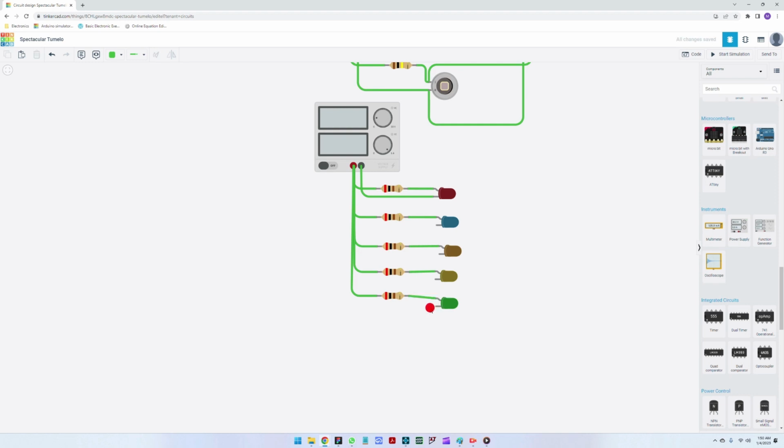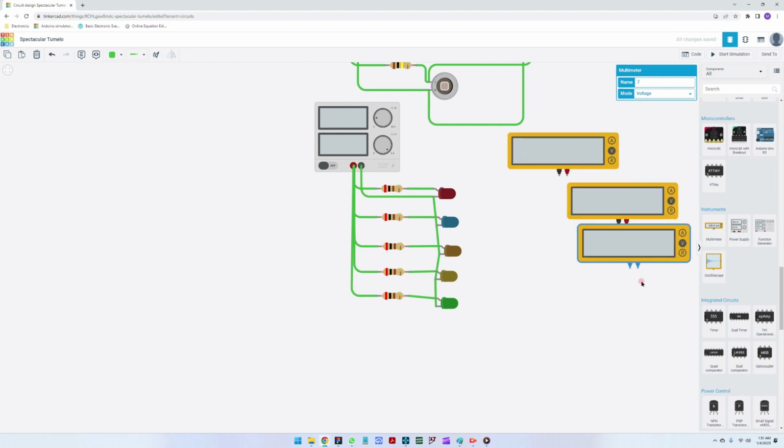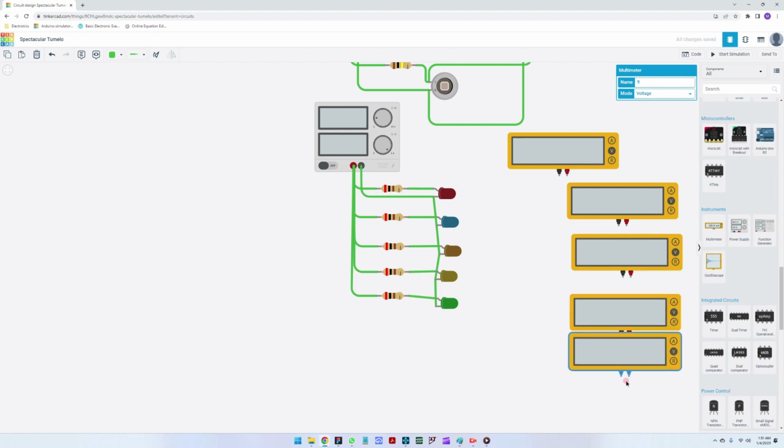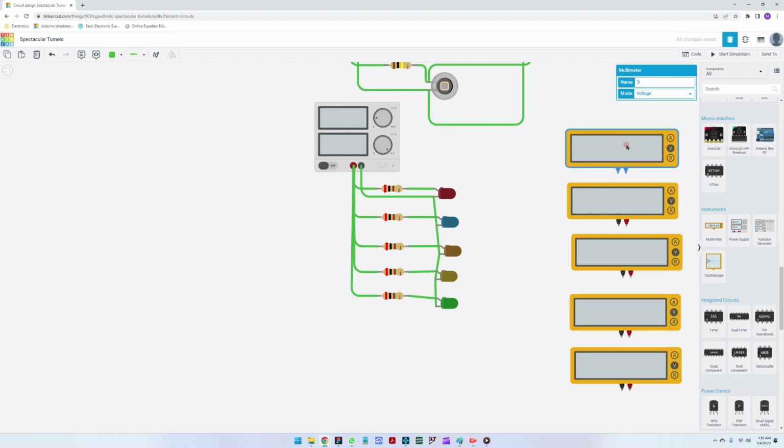The software also has this type of breadboard that you can use for creating this connection. And now we're connecting the grounds together. So I'm just gonna pull from here. And now the multimeter. What are we going to measure? Voltage drop. We want to see the voltage drop for different LEDs, so that we can get a sense on 2, 3, 4, and 5. Let me order them a bit.